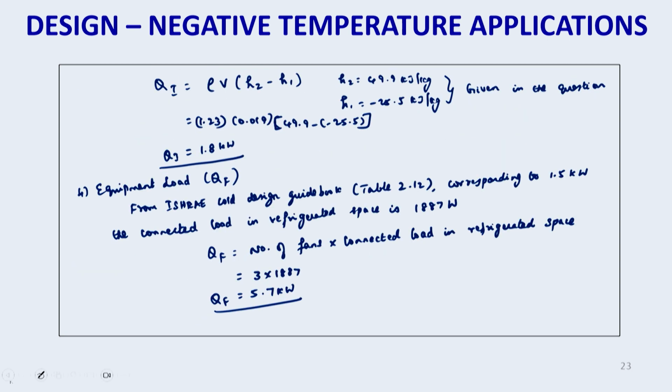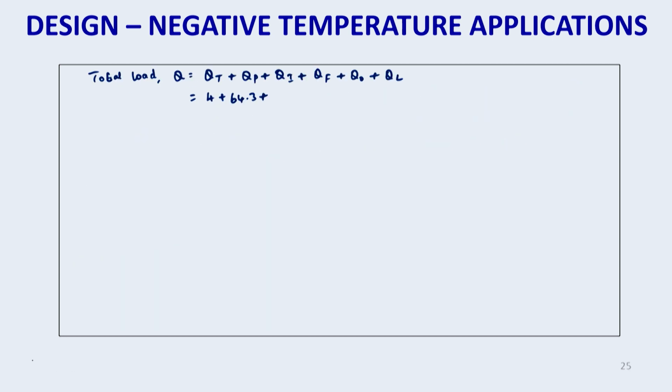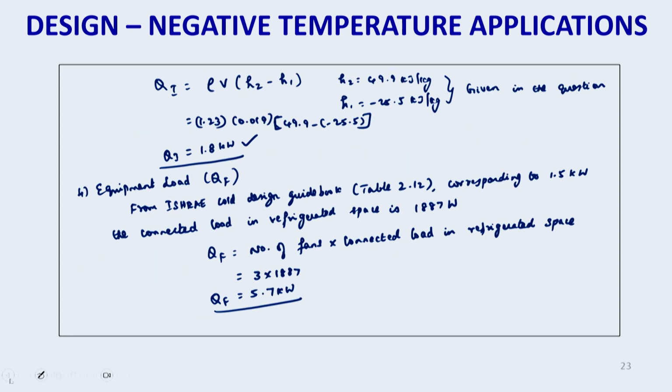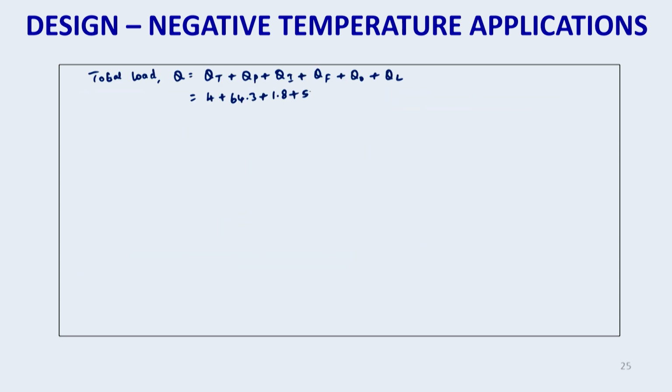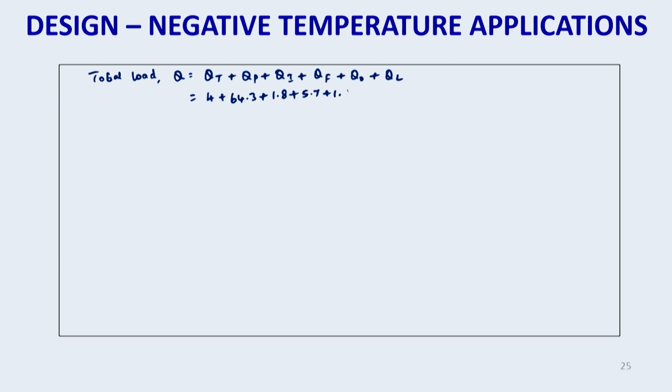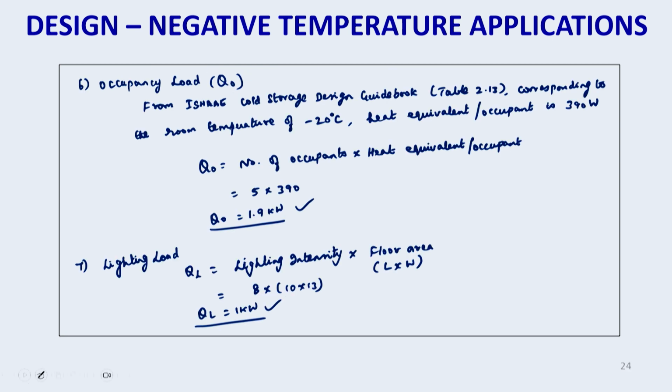Infiltration load 1.8 kilowatt. Equipment load 5.7 kilowatt. Occupancy load 1.9 kilowatt. And lighting load is 1 kilowatt.